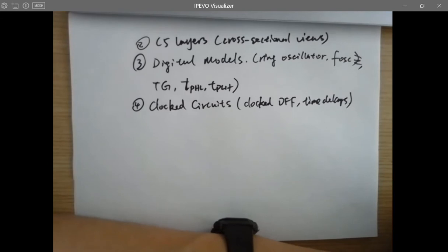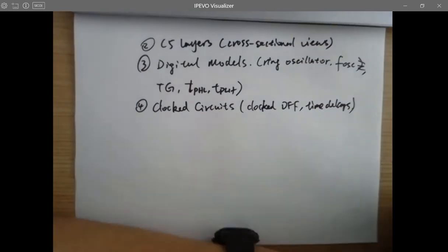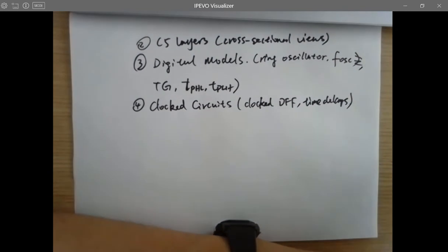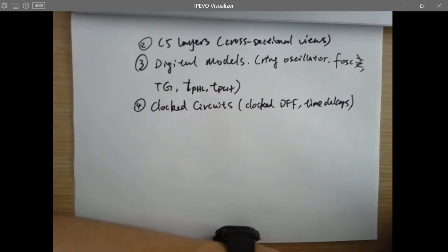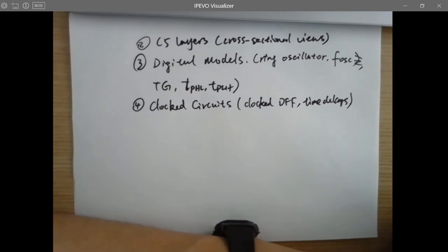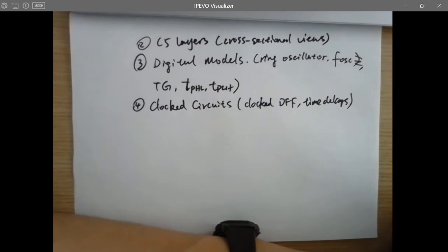And you have to think about, do you need to calculate, or if it's a transmission gate, is there a Miller effect involved or not? If it's a transmission gate, you pull the input on to the VDD, and the output will be put to VDD as well, right? Just one VDD, so there's no Miller effect. But for the inverters, it does have Miller effect. So the clocks will be totally different. I have exactly the solution on the lecture notes. Just definitely check out that notes and just watch the video if necessary.